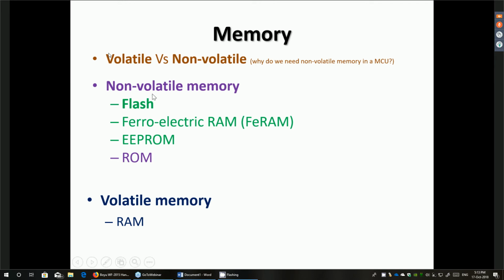So when somebody says flash, I know what technology was used to build that chip. I know special algorithms have to be run to write data into flash. When somebody says EEPROM, I know what technology is used to build that chip, and I can talk a little bit about the characteristics of that device. There is a reason I put these bullets in green, because they are reprogrammable. I can change the data. ROM is created by a mask. So ROM, by definition read-only memory, is not reprogrammable.